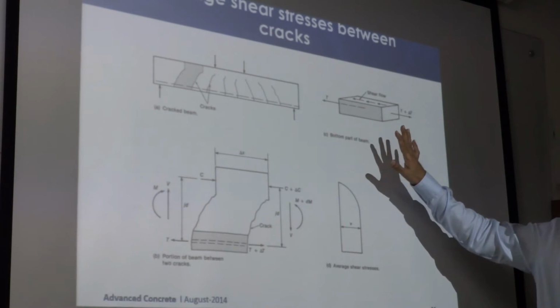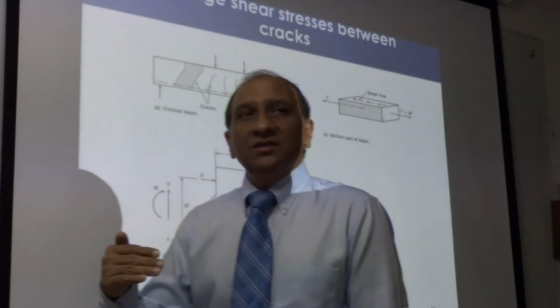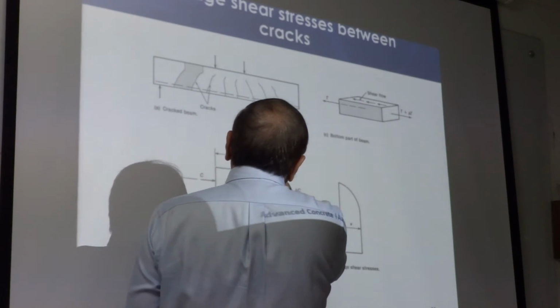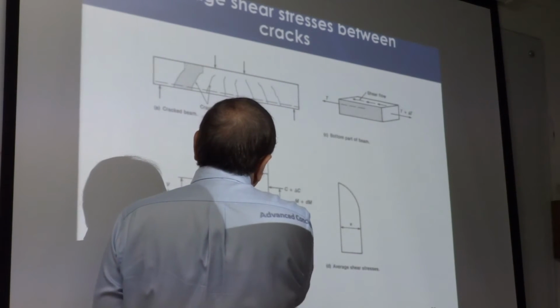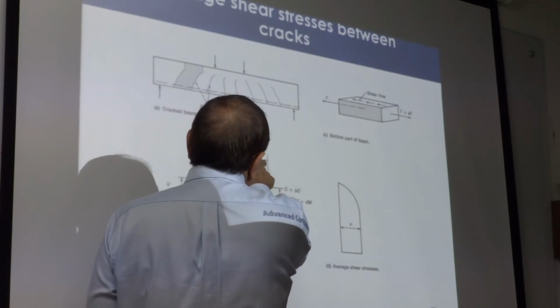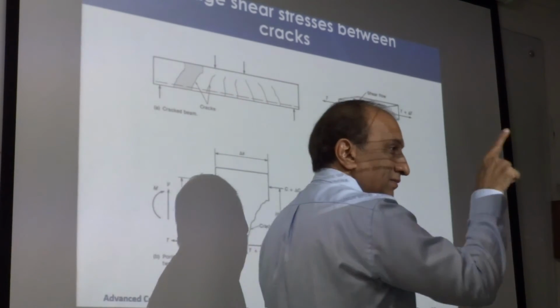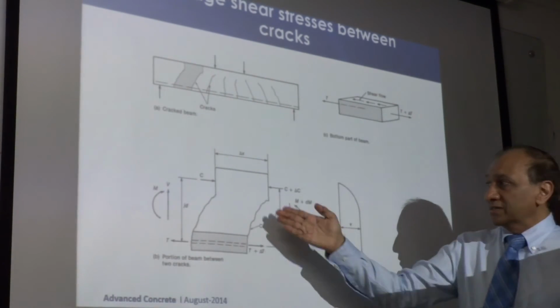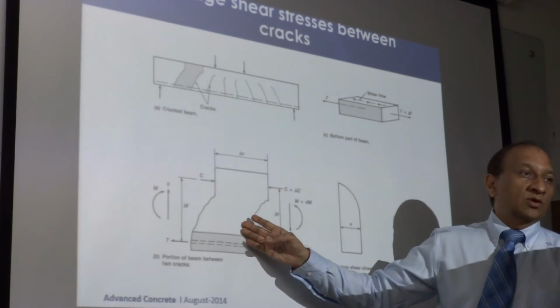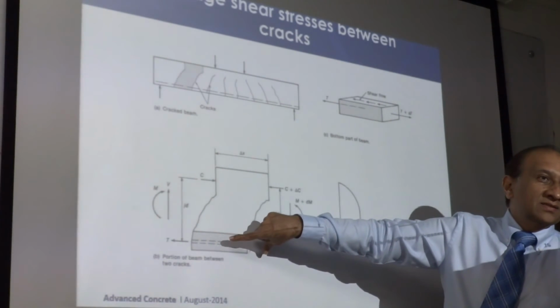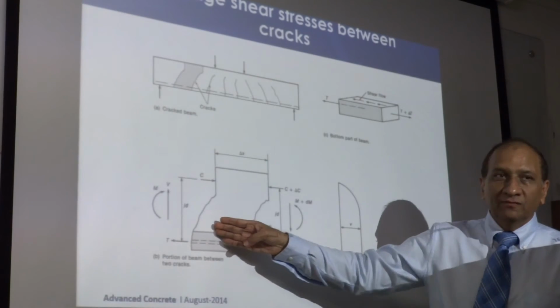So this is nothing complicated, just to give you an idea that the equations and theories are developed on the concept of average stress, and they take into account the crack spacing. This spacing is typically related to the D, approximately. This one, nearly. This is like a square, right? But sometimes these cracks can be closer together if the reinforcement is not provided properly. But for the purpose of design, we assume this to be the case, and then we can distribute the reinforcement in between.